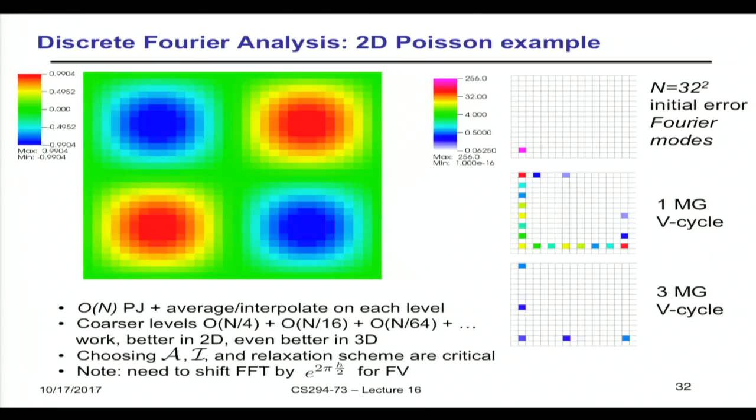There are also, again, if you have a jump in the problem so that you know that there's a physical kink, you can do interpolants that are one-sided, where you say, don't grab a value from the side where the coefficients or other values are different. Just work with a one-sided interpolant because we know it'll be more accurate than trying to interpolate through a kink, for example. So those are all options too. Good, thank you for the questions.